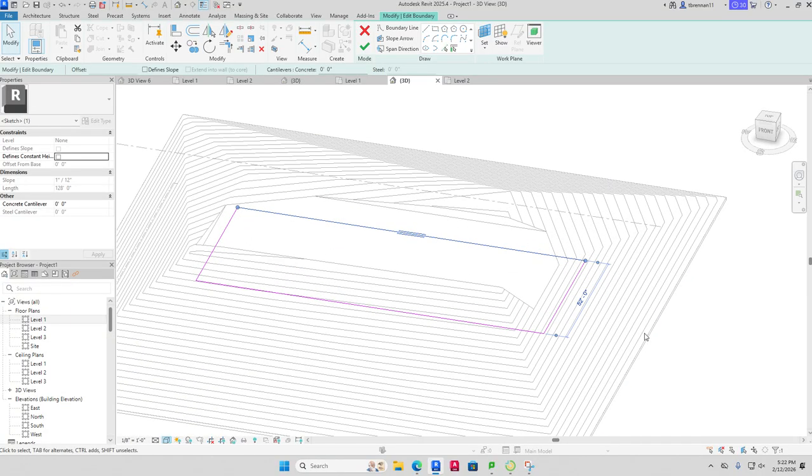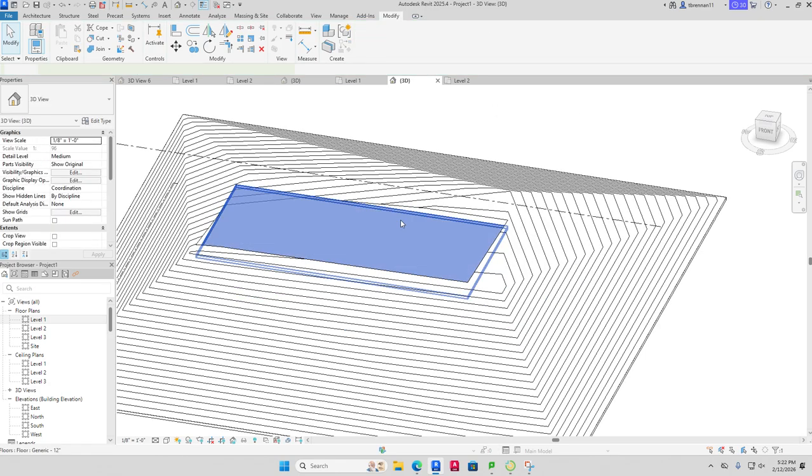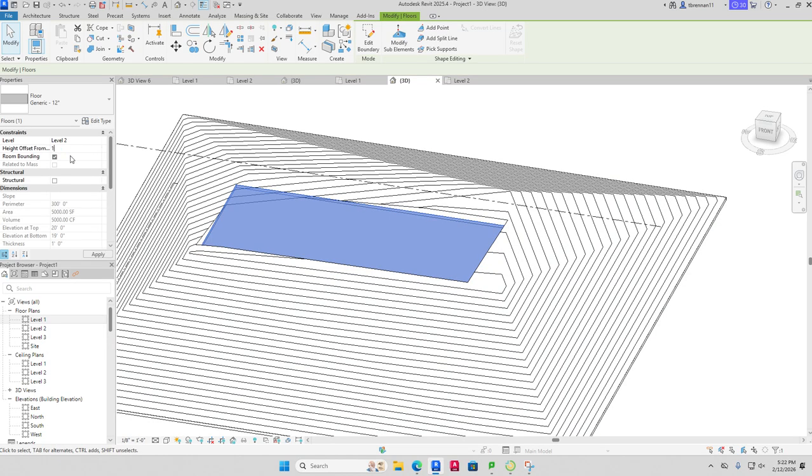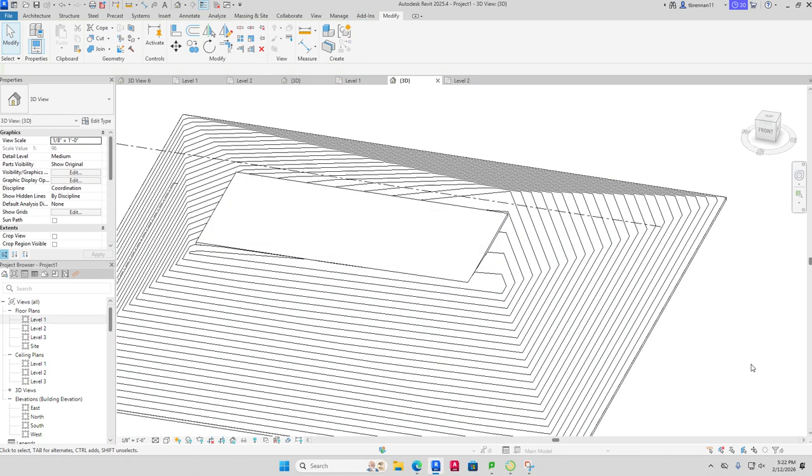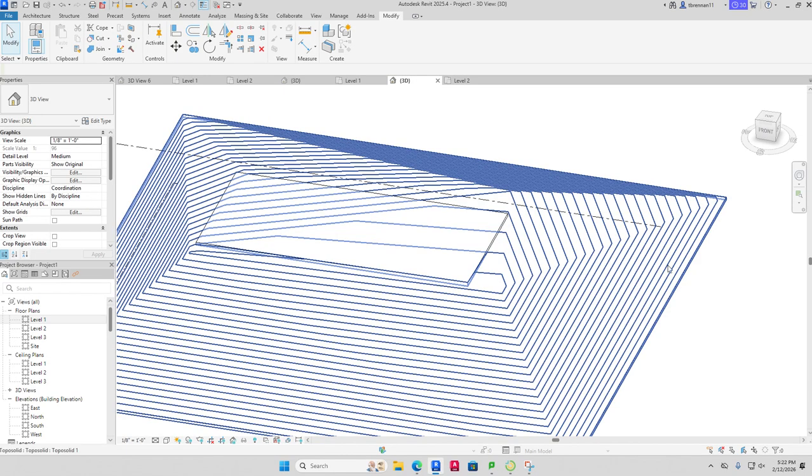We'll do that. Okay, the actual size this is going to be, I've spec'd this out here, and it's got to be 100 feet by 50 feet. So I'll make this 50 feet, and then the other side, I'm going to click on here, and make that 100 feet. And that fits pretty well on top of that. Hit the green check mark, and then we're good to go. That's sitting right there. I'm just going to bring that up a little bit further. Let's go 15 feet. All right, and that sits on top quite nicely. So that's like a 25-foot height.